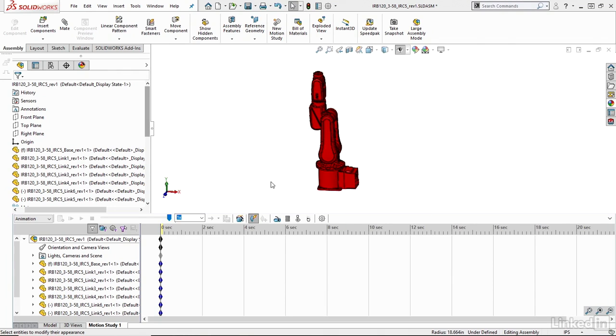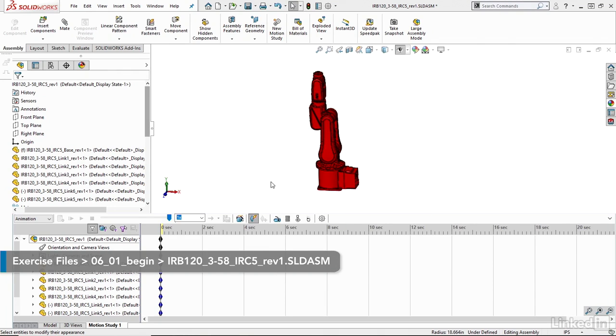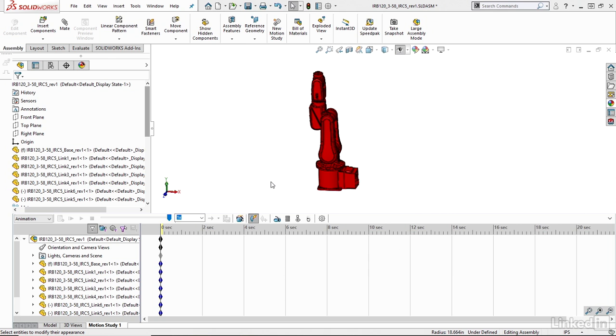Another method to generate SolidWorks animations is to use what we call motion drivers, specifically using mates to control and drive these animations. Using motion drivers such as mates can be a great option for generating animations that you want to have more fine control over. For example, we saw using the click and drag method, we could rotate an object about 45 degrees or so. But by actually driving the mates, we can make it exactly 45 degrees or have more exact values. Using these motion controllers, we have a lot more precision over our animations.